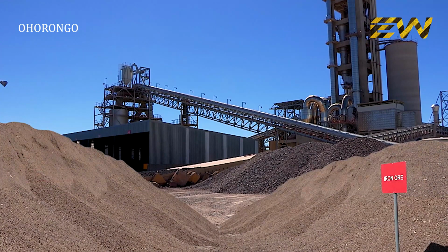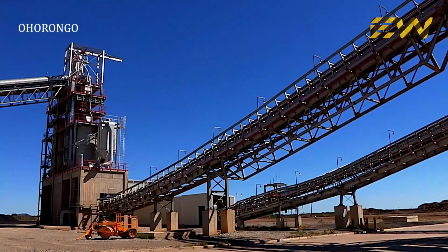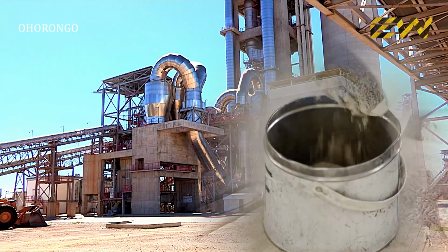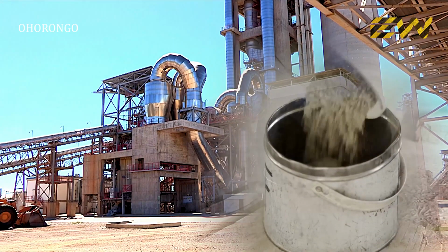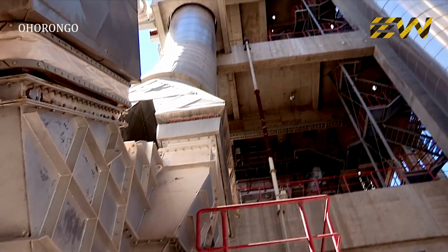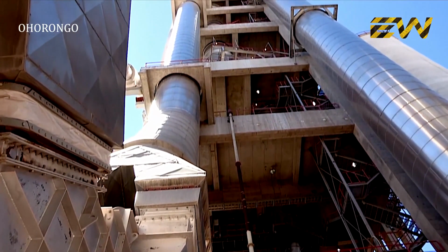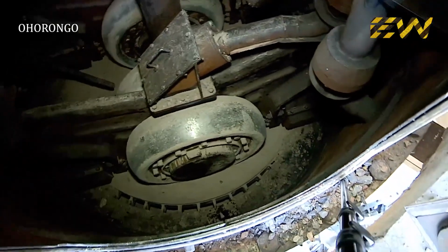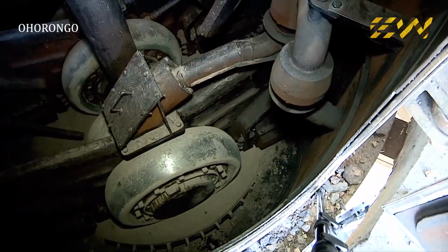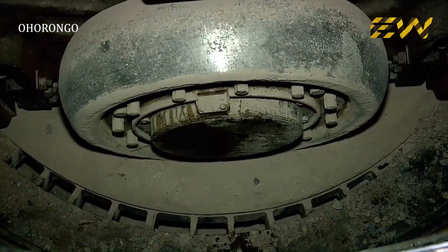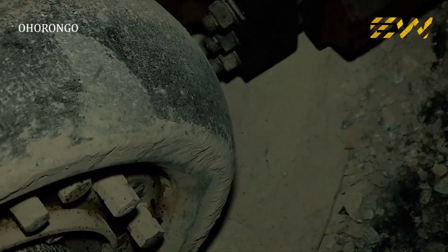Essential additives such as iron ore are added to the homogenized limestone, shale, and marl material, and this mixture is then conveyed to the raw mill, where it's ground to a fine powder which is known as raw mix. The mixture is dried by means of the excessive heat generated from the pyro process. The materials for clinker production are milled using roller mills instead of the traditional ball mills. The roller mills save about 30% on the total electrical power consumption compared to traditional ball mills.